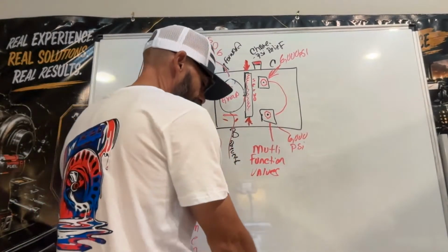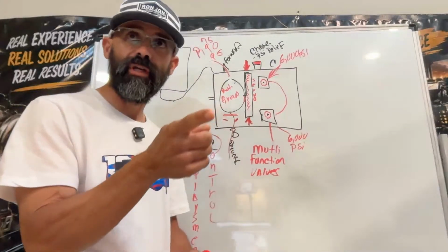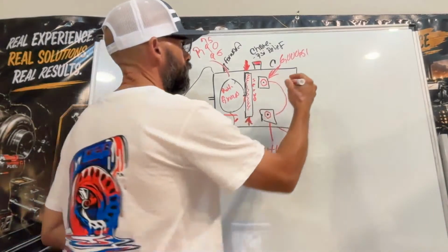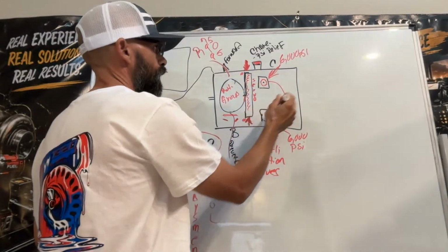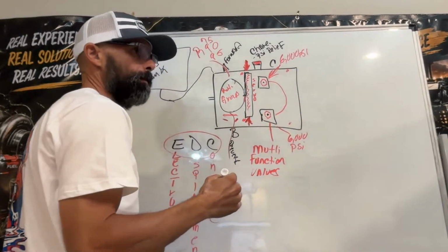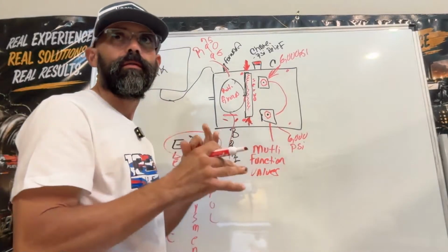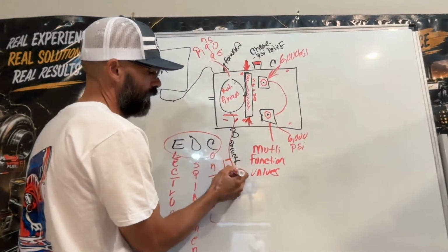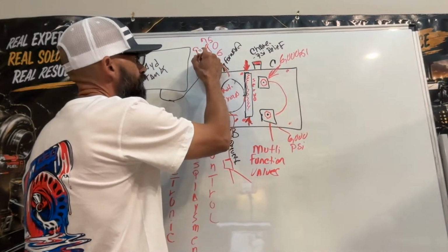So if you want to decrease your forward pressure and reverse pressure to 4,500 psi, my suggestion, and also Danfoss tells you to go up here. You're gonna see on top of the EDC right here, right, and also on certain ports on the pump, certain places that you can put a hydraulic gauge, so you can get readings straight from the pump. But also you can tee off out of port B, right, with a gauge, and on port A also you can put a T with a gauge.